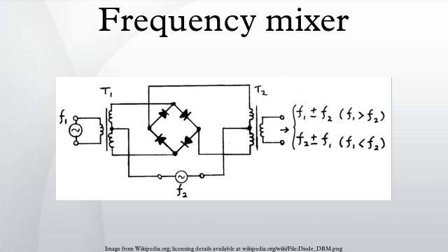Switching: another form of mixer operates by switching, with the smaller input signal being passed inverted or uninverted according to the phase of the local oscillator. This would be typical of the normal operating mode of a packaged double-balanced mixer, with the local oscillator drive considerably higher than the signal amplitude. The aim of a switching mixer is to achieve linear operation over the signal level, and hard switching driven by the local oscillator. Mathematically, the switching mixer is not much different from a multiplying mixer, just that instead of the LO sine wave term we would use the signum function.